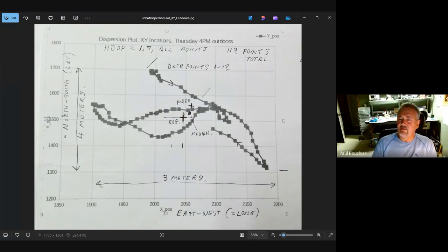Well, the other thing that I get from my understanding is much faster startup. Yes, or much faster convergence on a fix is perhaps a better way to express it. It was particularly noticeable when I had an RTK setup back in the 2010 or 2012 timeframe. It only had L1, and to get an RTK fix took about 5 minutes, versus with L1 and L2 you get an RTK fix probably inside of 30 seconds.